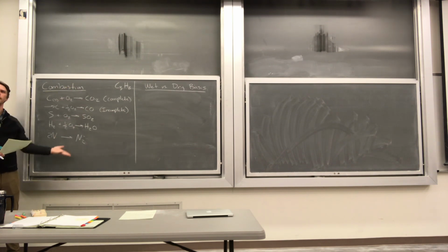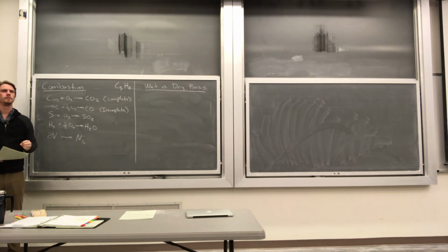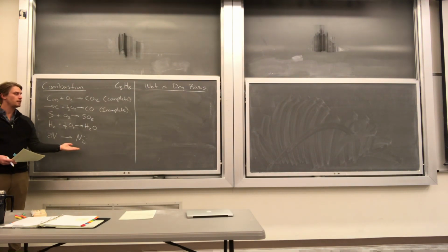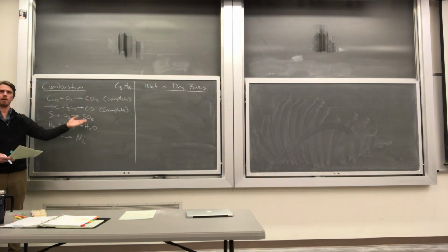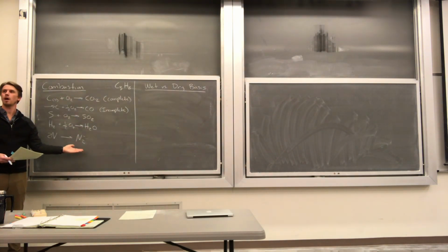What is unique about water compared to these chemicals? It is a liquid. At room temperature, it is a liquid. I would also accept that it is a subcritical fluid. So a supercritical fluid, we cannot condense it to a liquid, right, just by pressurizing it. So if we cool down a flue gas stream, which is the product of a burner, we can condense out the water.